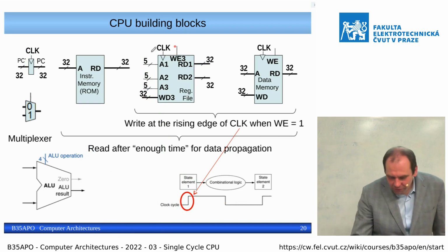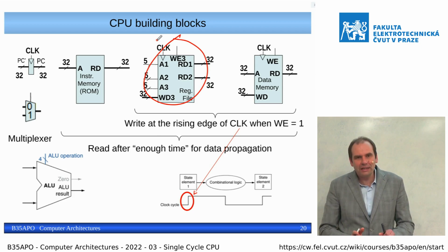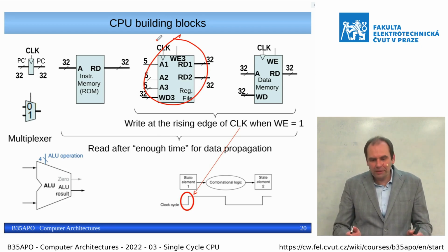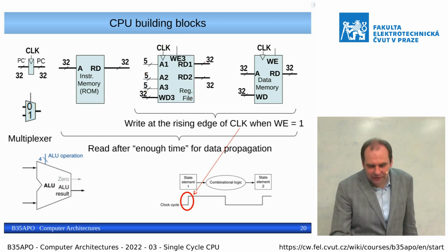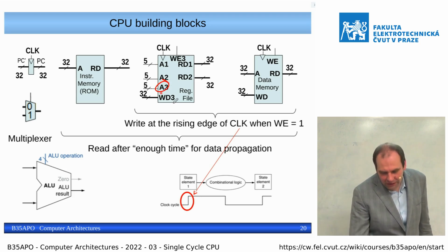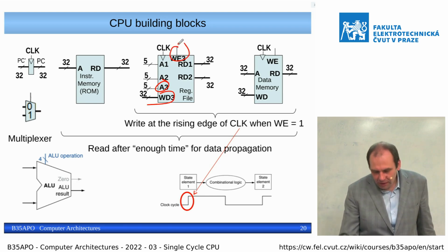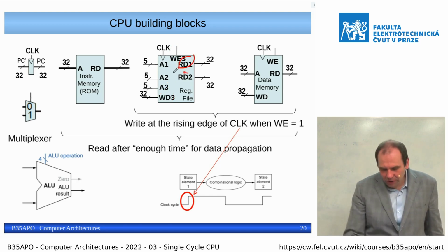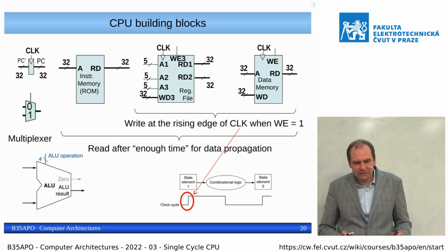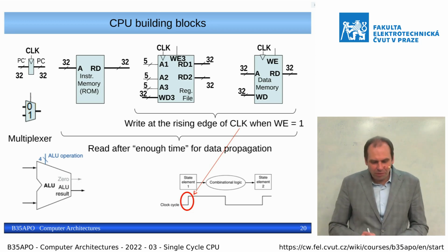So it is the register file. Do you see this data structure or what it does? Basically it is an array of 32-bit values in the memory, where we can at a given instant of time write at one index a value which is on the write data, but not each time, only when we want to write it. And in parallel we can read 2 values in this case. Sometimes we have register files which allow access to even more data in parallel, but for our actual case this block is enough.